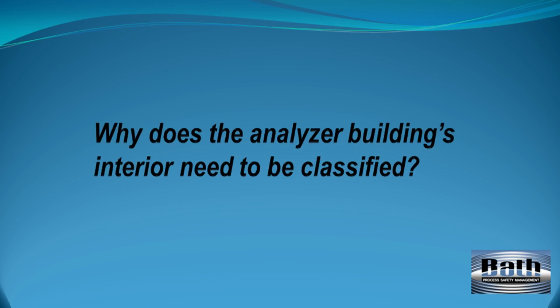Why does the interior of analyzer buildings need to be classified? The answer to this question must be addressed in two parts. In the first part, the hazardous area classification assigned to a room or building is based on its intended purpose. The main factor centers around the material analyzed within the building.